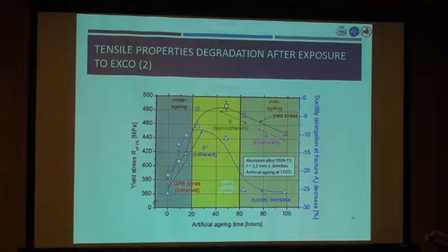So this is a summing up of all the results. Here in the black line you can see how yield stress goes. It is essential to point out the underaging, peak aging, and overaging conditions. And here you can see the ductility decrease, meaning that if you associate it also with the precipitation sequence, when you have coherent particles, then the ductility decrease is less.